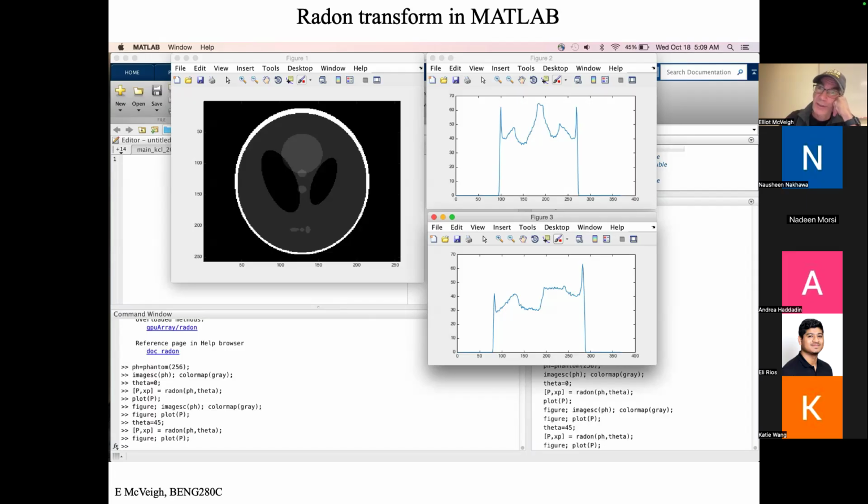And so rather than the Ram-Lak filter, you use a modified Ram-Lak filter where it still goes down to 0 at the origin, but it doesn't keep rising up, up, up as you go to high frequencies. It comes up and then you roll it off. So it starts looking more like a smoothing filter, and that's called the kernel of the reconstruction.